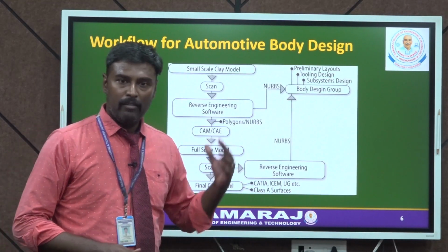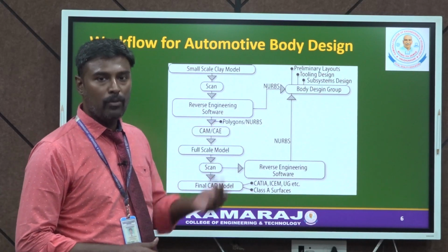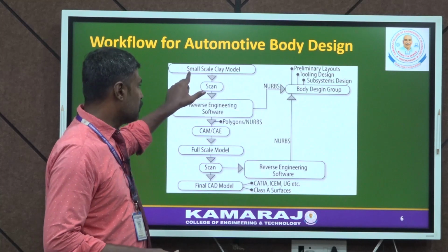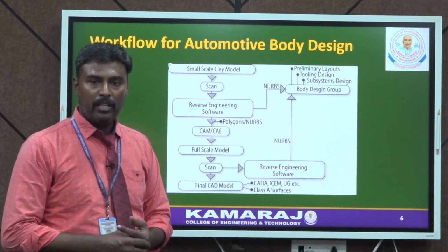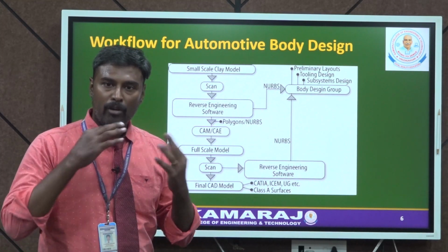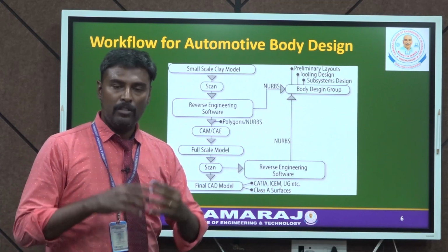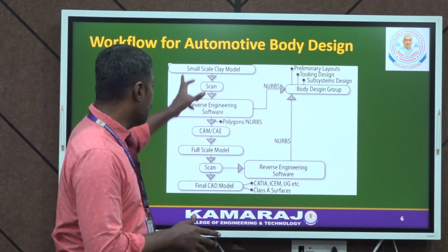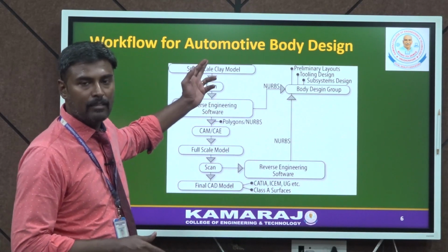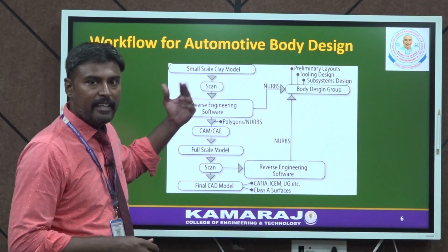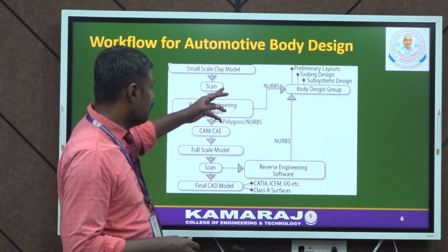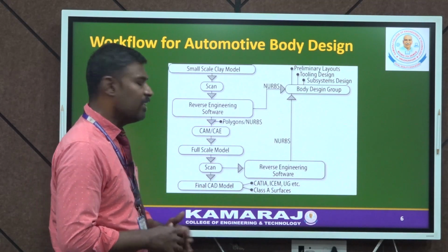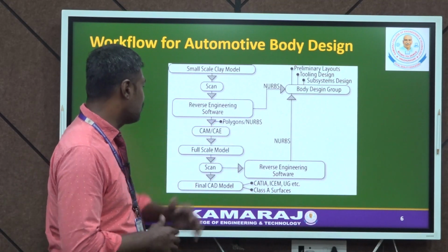Before we start, we will explain the process flow of reverse engineering in the automotive sector. First it will start with some small scale clay modeling. Whenever you go for component modifications, initially engineers will work using a clay model. After making the clay model, they capture it using a data scan, that is 3D scanning. Using this data acquisition device, they capture all those data points and convert them into an initial CAD modeling software through the reverse engineering software.